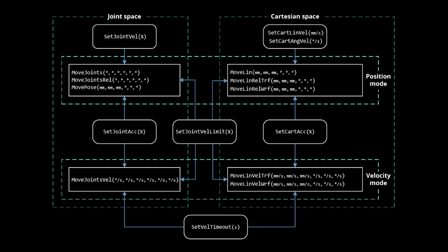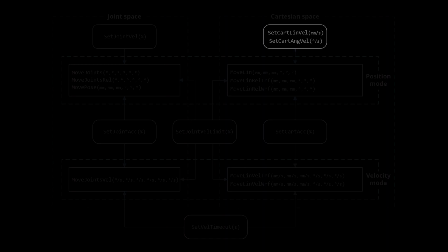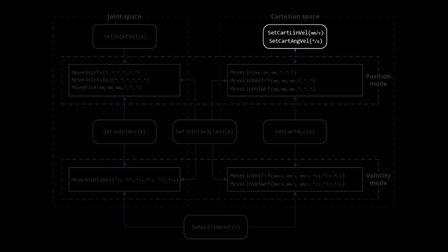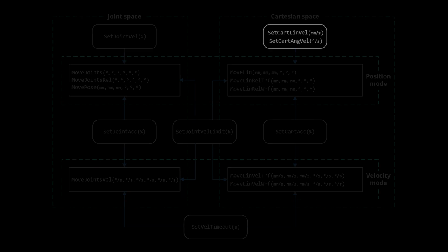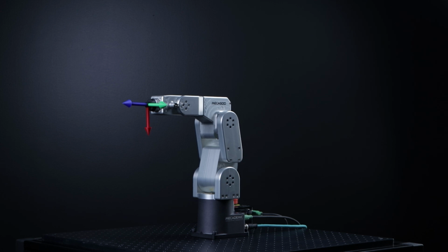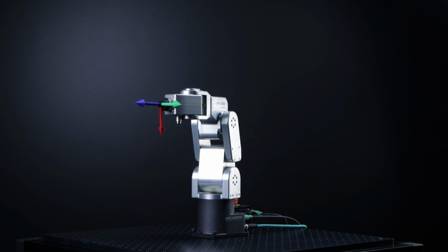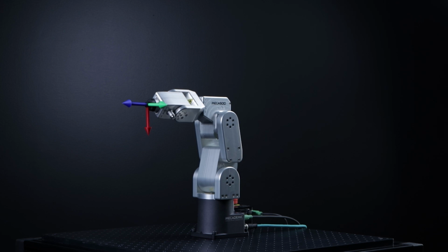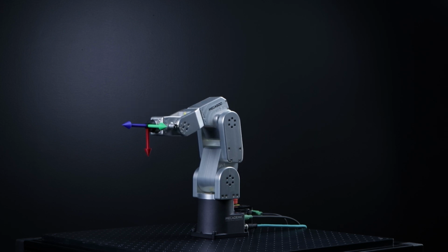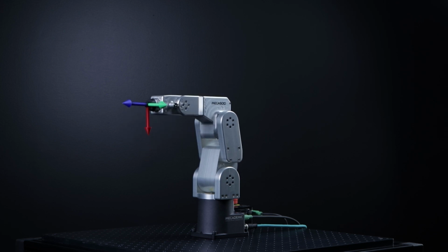Linear moves can be affected by changing their velocity and acceleration. These following commands can be used. There are some things to note about linear movement velocity. While it's possible to specify velocity values for linear moves, there is no guarantee that the robot will reach them since it does not pre-compile the program to check if all the moves are possible. It's all done online. If the robot cannot reach the velocity target, it will go as fast as possible.